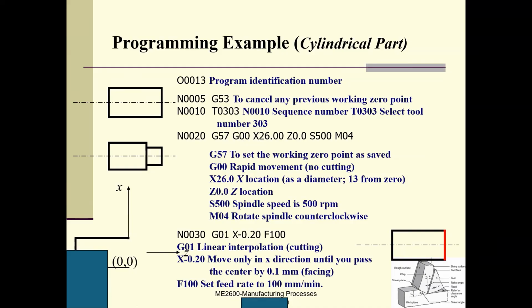So this position, X20.6, Z0. This is X. Be very careful: the vertical one is X, and the horizontal one is Z. Okay? This is kind of counterintuitive, but for our case, be very careful. This is your X, and this is your Z. G00 means from this position, without any cutting, I go in a straight line to this destination. This is my destination number.